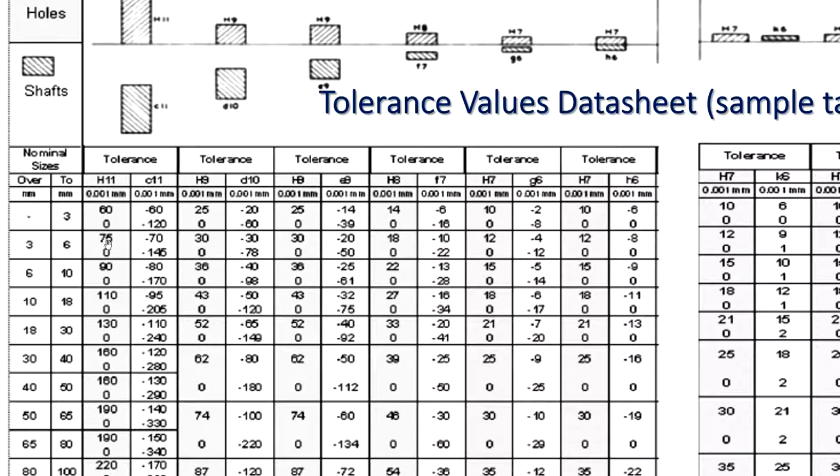So here if you look at the hole, the lower size for the hole is 0, and the upper number is something, because you drill the hole with a drilling tool. So the hole diameter cannot be less than the drill diameter. It can be a few microns more depending on the type of reamers or broach you are using, or how much time you spend. If you drill it and just stay there, okay, fine. Or you drill it and keep drilling to clean all the last pieces of chips and the burrs, it will remove a little more material and be a few microns larger. But in any case the hole size cannot be less than the size of the drill which you are using. So that's why here the lower number is 0, and the upper number is a few microns.